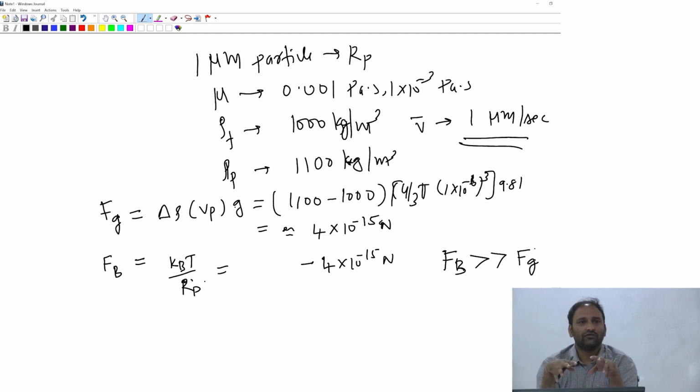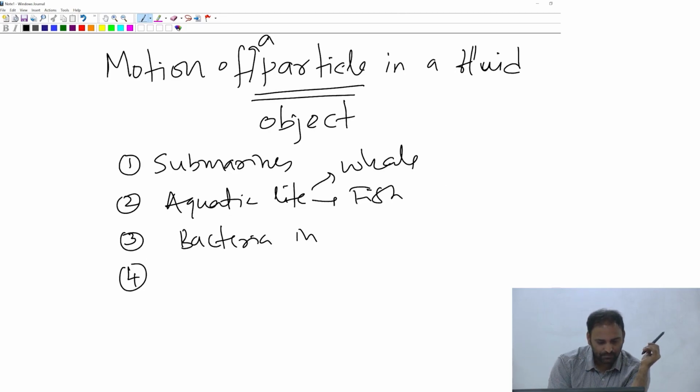Therefore, whenever one is working with a fine particle system, it's a good idea to think a little bit about the different forces that are acting and also do a simple calculation of the different forces that will be acting on the particle. That will give you some information about whether your gravitational forces are really important in terms of making your fine particle dispersion unstable.